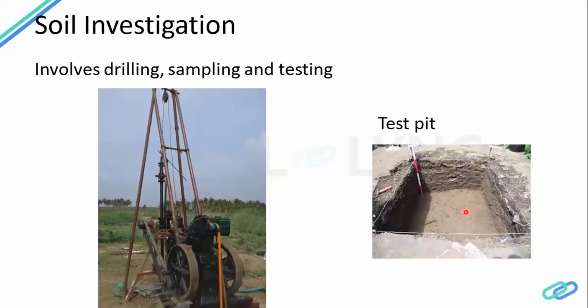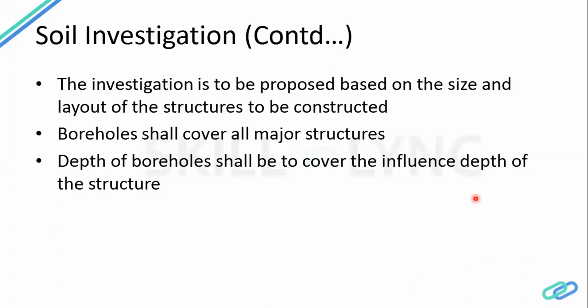But the disadvantage is that we can go to a maximum of 1 or 2 meters depth, or at most 3 meters. More than that, it will require some shoring system, which will make it more expensive. So in case of getting more data, we'll go for the SPT test. As I said, we have to position the boreholes in such a way as to get the data for the entire site. So the investigation has to be based upon the structure we are going to build.